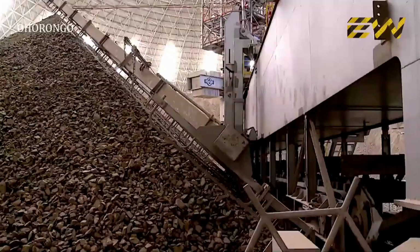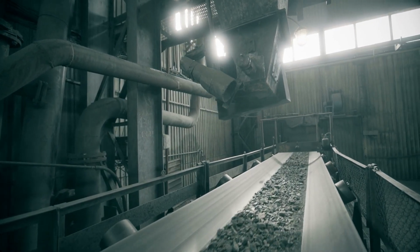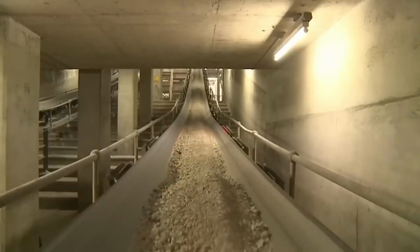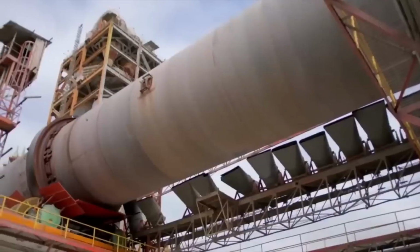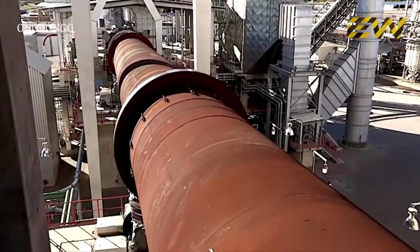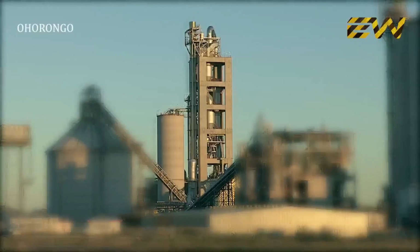To produce cement, the crushed limestone and clay must be combined and pulverized into a fine powder called raw meal. Conveyors transport the crushed limestone and clay into measured hoppers where the materials are mixed to the proper proportions. This raw meal mixture is then fed into the raw mill, which contains a large rotating steel drum. Powerful steel balls within the mill pulverize the raw meal into a fine powder as the drum rotates. The fine raw meal powder exits the raw mill and enters the preheater tower.